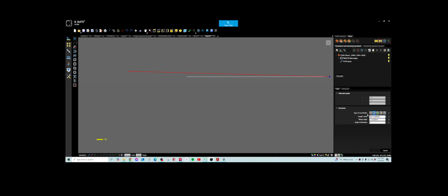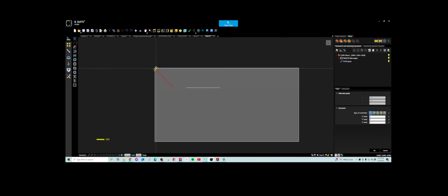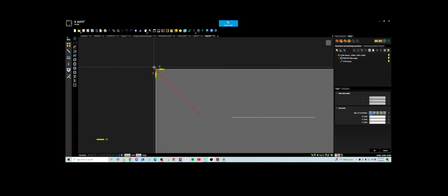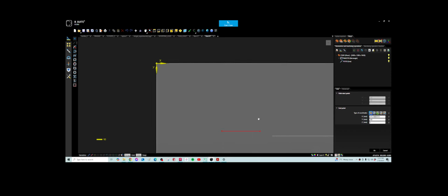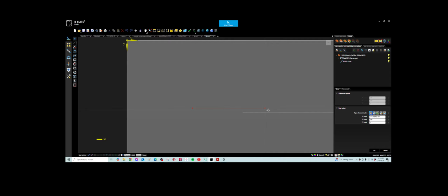But if you change to the first one, this is absolute coordinates. That means whatever you put here is related to the origin, which is here. Here is the point 0, 0. Here is your origin, right? So usually, depending on the case, of course, I change this if I know the length of whatever I want. So I'm gonna put 300 as well, and that's it, right?